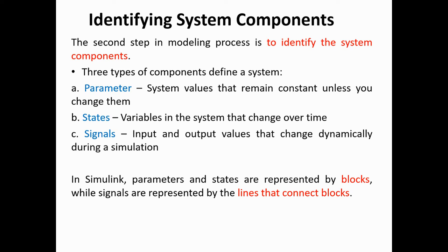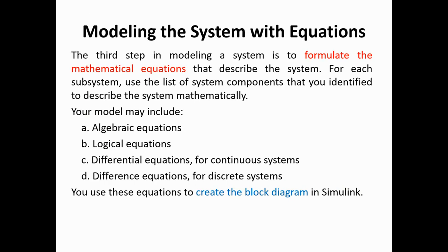So once you have clarified all of those design components, the next thing to do is model using equations. The equation could be an algebraic equation, or in our case, logical equations. But if you do dynamic systems or complex control systems, you might need to use differential equations or advanced mathematics to develop the equations. You can do the transfer function if you are designing, for example, a DC-DC converter or a buck-boost converter circuit.